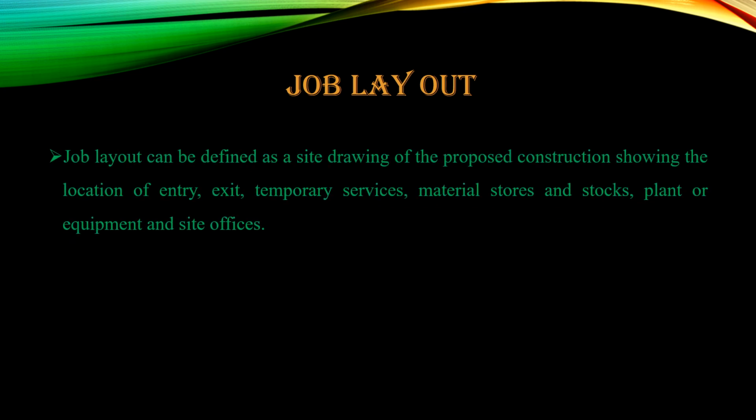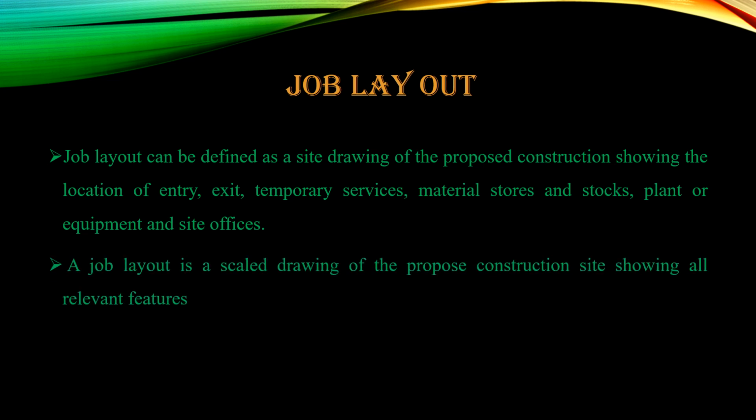construction site. Next is another important topic I am going to brief about, which is the job layout. Job layout is an important portion. Job layout can be defined as a site drawing of the proposed construction showing the location of entry, exit, temporary services, material stores and stocks, plant or equipment and site offices. A job layout is a scaled drawing of the proposed construction site showing almost all the relevant features in that particular site.